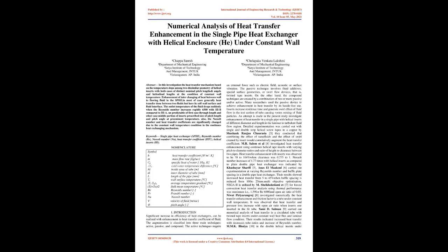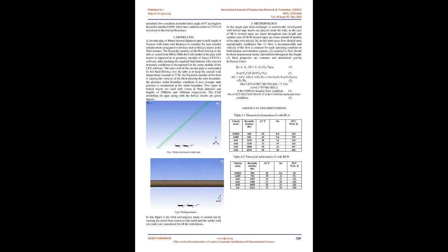Nomenclature. Symbol. 1. Introduction. Significant increase in efficiency of heat exchangers can be realized with enhancement in heat transfer coefficient of fluid. The augmentation is classified into three main techniques: active, passive, and compound. The active techniques require an external force such as electric field, acoustic or surface vibration. The passive technique involves fluid additives, special surface geometries, or swirl flow devices, that is, twisted tape inserts. On the other hand, the compound techniques are created by a combination of two or more passive and or active.